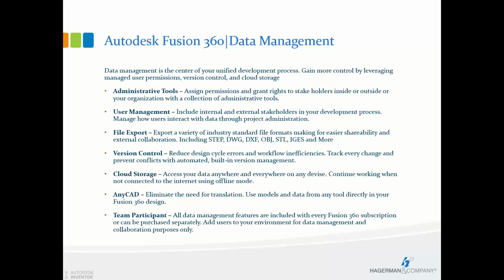There is a multitude of export tools where you can save out STEP files, DWG files, DXFs, OBJ or STL mesh files, and many more. And we'll see that within the tool itself, we have version control. We can go back and look at that design history in a couple of different ways. As we mentioned, it's got cloud storage, so your files are out on the cloud. Safe access and specific assigned access. Only the users that are assigned the rights to view a given project can get in and see those items.